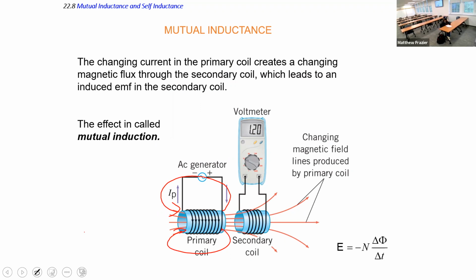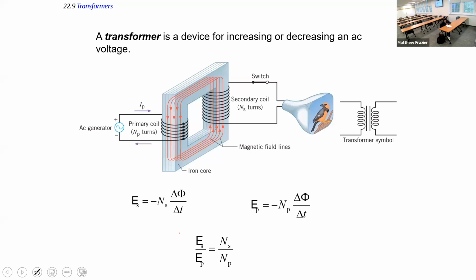To increase the efficiency, you want to increase the density of the magnetic field. And one way to do that is to use, not specifically a conductor, it's got to be like an iron material, a ferrite. It's got to be something that will condense the magnetic field, that will attract the magnetic field into it. So a ferromagnetic material, let's say. That's close enough. That makes it more efficient.